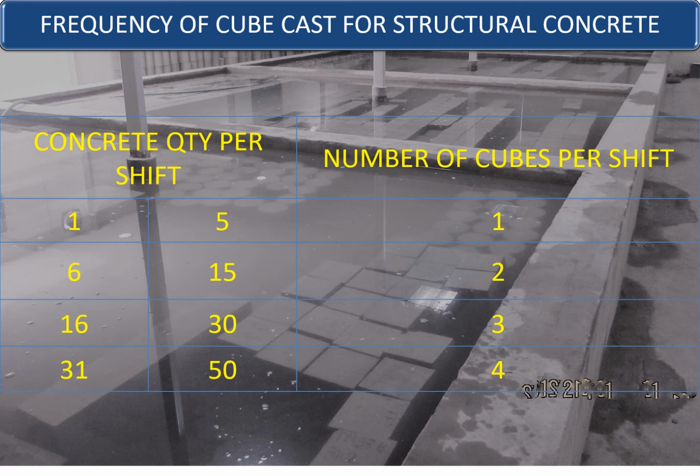In case you require additional cubes to be tested for 1 day, 3 day, 7 days, or 14 days, you need to incorporate those values in the calculation sheet. But by default, we have considered one sample to be tested for 7 days, and the rest based on the IS 456 requirement, which is being used in the calculation for determining the number of cubes required and the size of the curing tank.